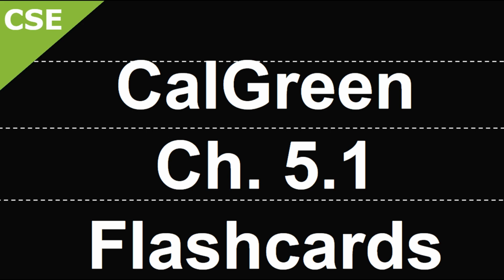If the total number of actual parking spaces for a new building is between 0 to 9, then 0 EV capable spaces are required and 0 electric vehicle charging spaces are required. If the total is between 10 to 25, then 4 EV-capable spaces are required, and 0 of those need to be electric vehicle charging stations. If you're providing 26 to 50 actual parking spaces, then 8 EV-capable spaces are required. Of those 8, 2 must be electric vehicle charging stations.